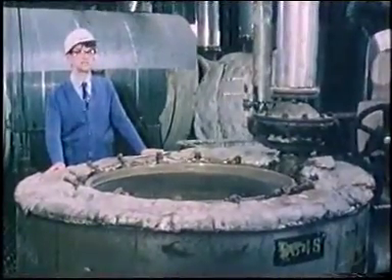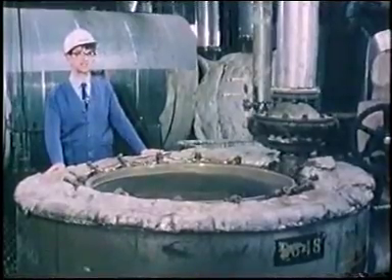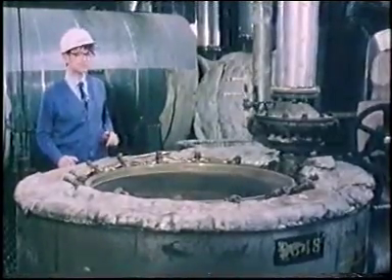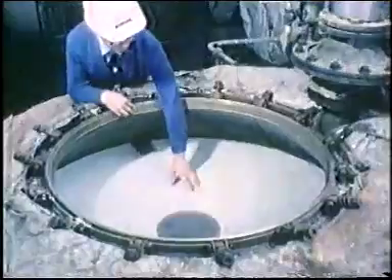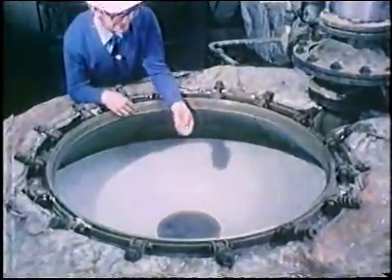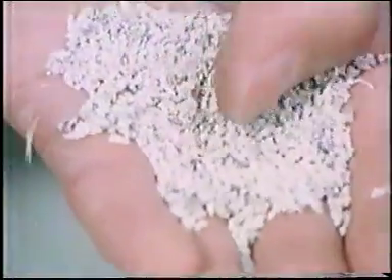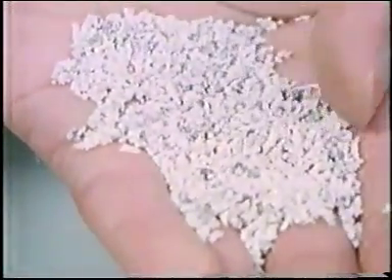The heart of the plant is the reactor vessel where the chemical change takes place. Here's one that isn't in use and we can look inside. This is the bed of catalyst, and it's about 2.5 or 3 centimeters thick. The catalyst is silver, and at 1979 prices, the bed would cost about £15,000. But the silver is a catalyst, and so it is not used up in the chemical reaction.